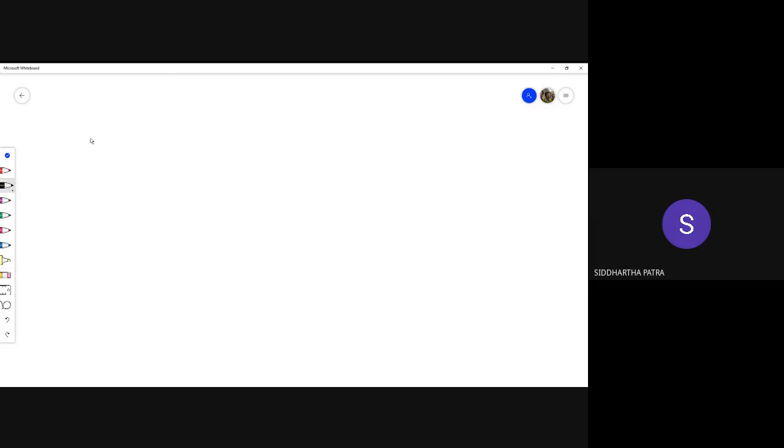So our interest is with this matrix, taking the gradient of the shape functions with respect to the physical coordinates. The individual terms are del Ni del xj, again a 4x2 matrix.